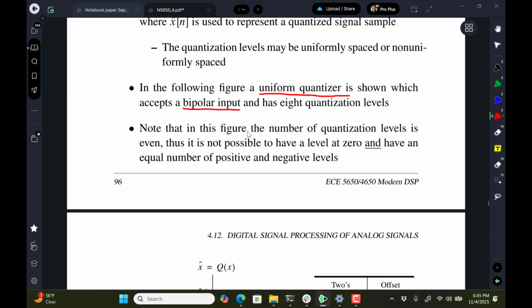Now, if you have an analog type waveform like audio or speaking, what are you going to do if your converter can only start at 0 and go to 3? You have to use some sort of level shifting in your electronics to move your signal, which is bipolar, as speech is, and center it at a halfway point in the biasing. But I'm not going to really dwell on that. I'm just going to make the idealizing assumption that our quantizer is bipolar, and if it's not, we manage that.